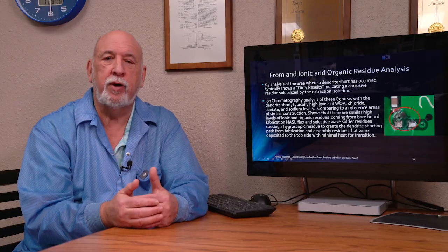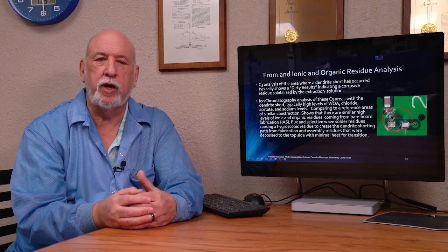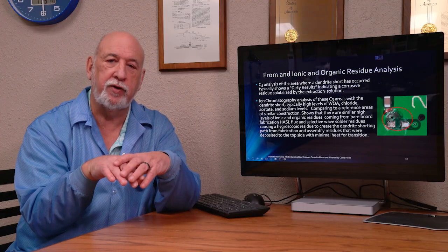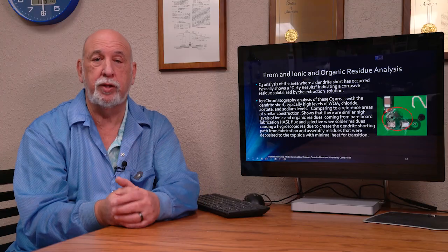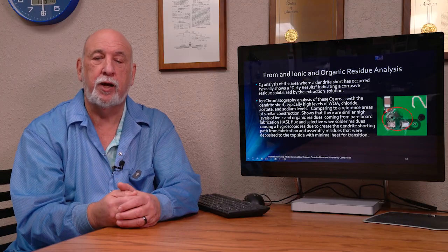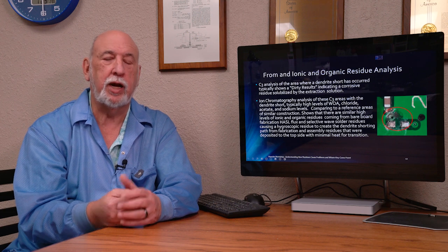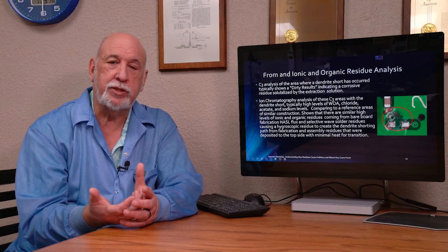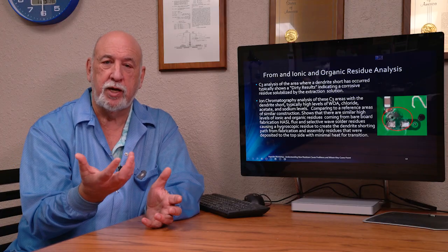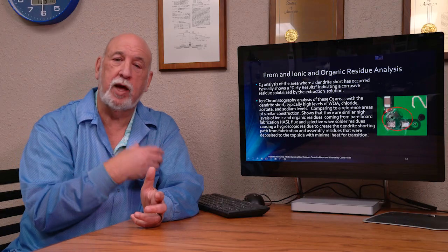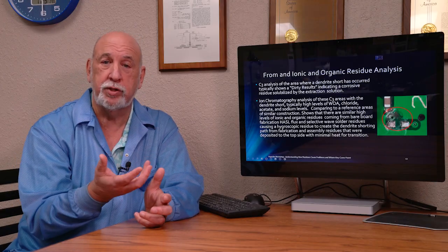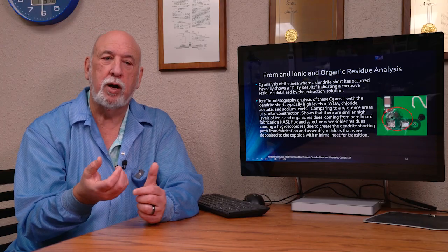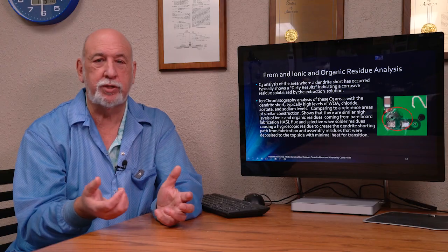Ionic residues come from the soldering operations where flux travels from the bottom side of the board to the top side of the board, either through a cloud effect, through vias, or through the leads, where it's fluxing and trying to get enough flux in the barrel to allow for good wetting. What happens is that flux comes to the top side but doesn't see enough heat. There's not enough topside heat because you don't want to disturb the solder from the first reflow process. So the residues that are there are still moisture absorbing and still strong acids.